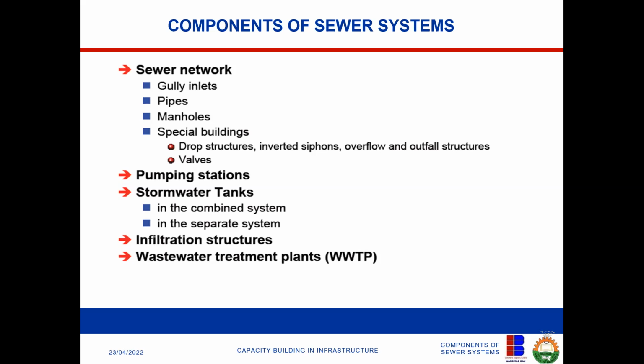Sometimes it can be 6 meters, sometimes it can be 12 meters. I have seen treatment plants where the difference between the head at the inlet of the wastewater and the treatment plant is about 12 meters. So when it gets to the treatment plant, you will need to pump it back up into the tanks, because flowing by gravity means you need to slope down so it can flow very well. And the sloping must be done perfectly to avoid blockages, right?